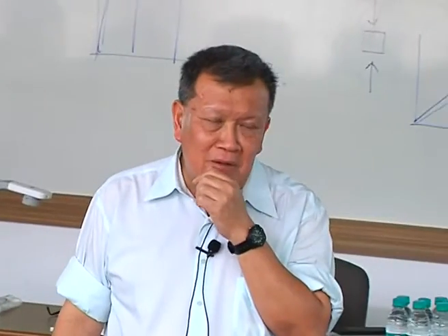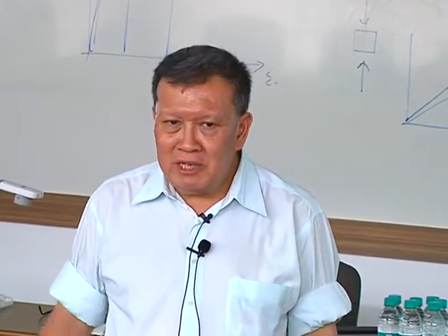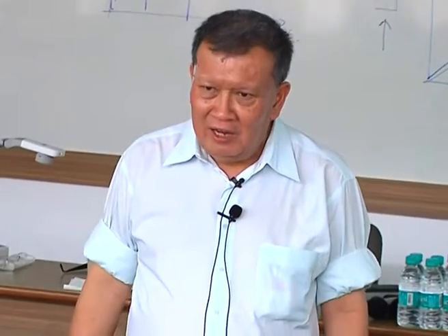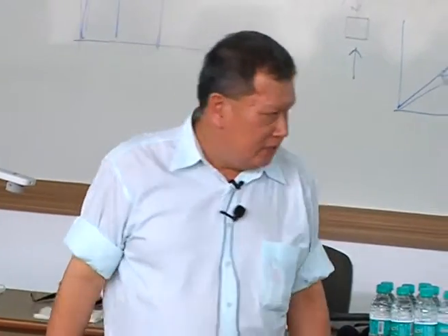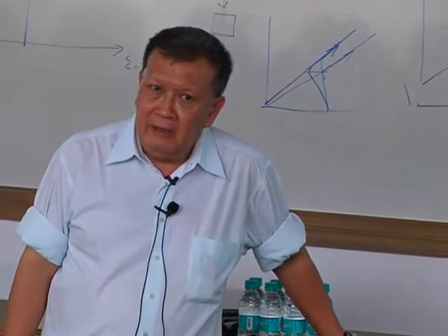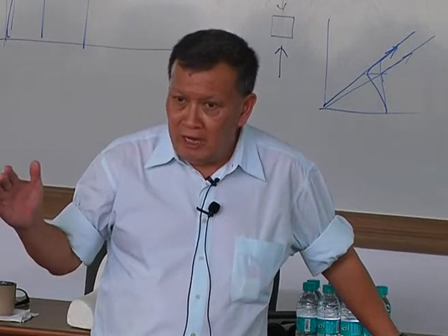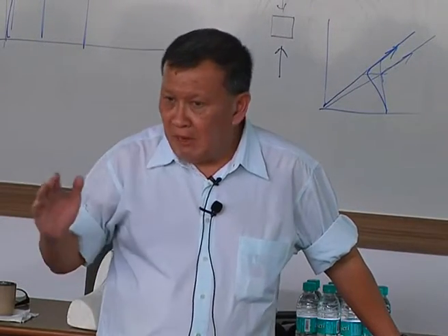Oh, applicability of Cam-Clay. Usually people don't apply Cam-Clay to sandy soil. You remember when you say sand, people will say, let's go Mohr-Coulomb. And in a sense, there is a reason for it, because very sandy soil has a cap, but the cap is very far out.